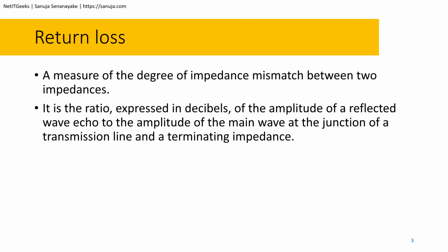So if you have an untwisted termination point or a very loose termination, that could cause a lot of impedance. In terms of frequency, cable length is another problem that will result in return loss.